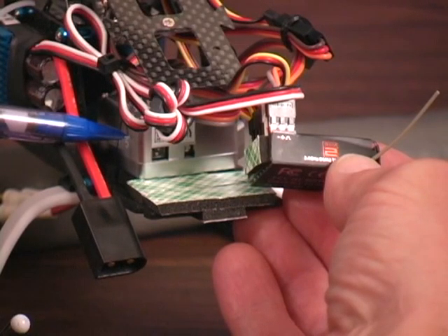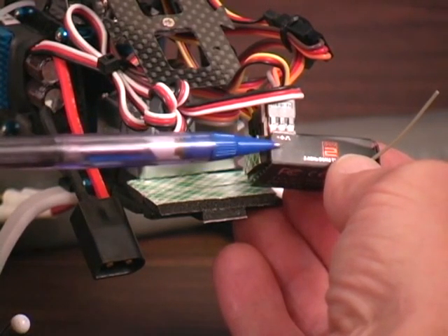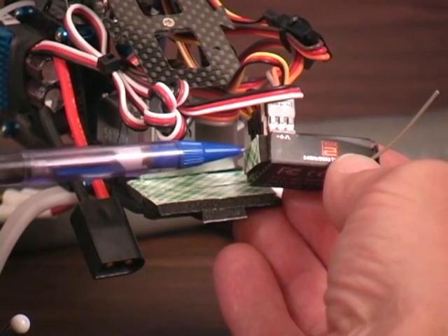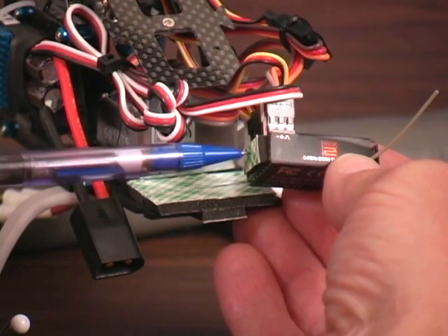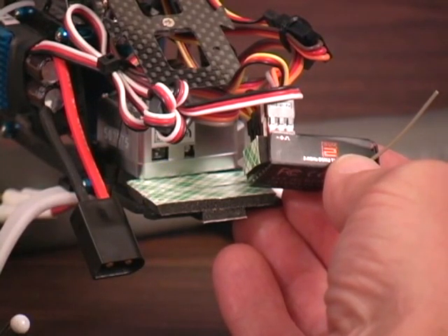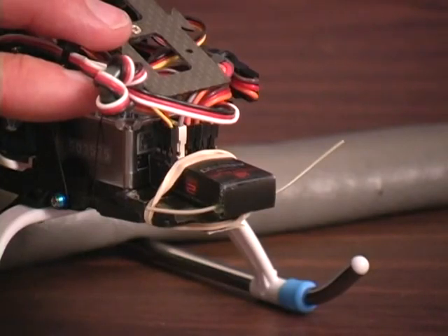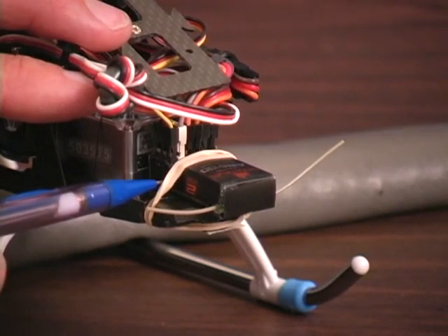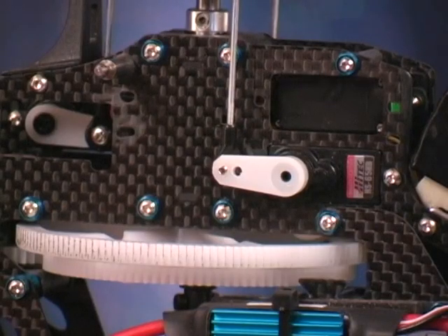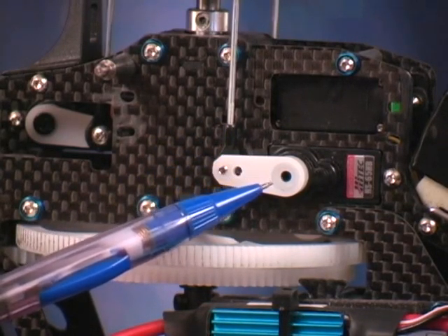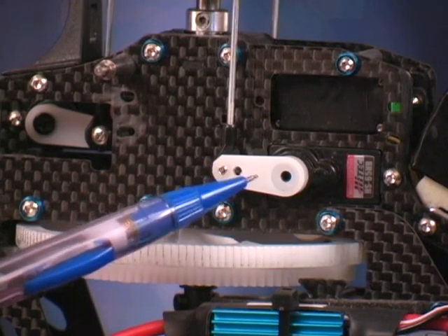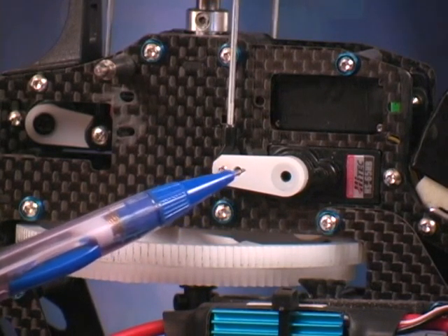With the gyro adjustments completed, I can mount the receiver to the front of the plate. I've used a little piece of Ace foam tape here. This will bump right up against the gyro, and I'll go ahead and remove the backing and stick the receiver down. For additional security, I've added 2 small rubber bands around the receiver. Now I'm going to screw in the servo arm screw, and then in preparation for the powered runs, do a nice detailed pre-flight over the whole machine.